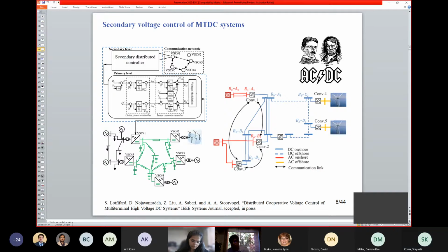No, you have a reference point. In a centralized setup, you have one centralized controller, and it communicates with each inverter individually. But here, in terms of the multi-agent controller, there is what is called the leader node. So you have a leader at one point of your system, or it can be any point of your system. The leaders communicate, and the reason it's called fault tolerant is that you can have as many leaders as you want.